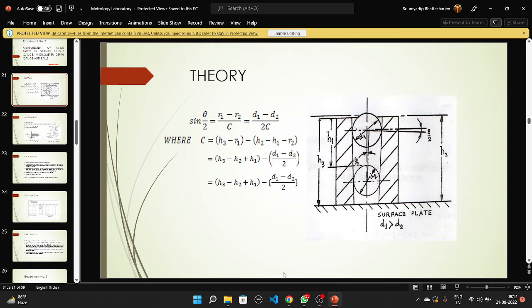Taper is basically the external taper. Now, the hole into which it is entering is also a kind of tapered socket, right? So taper in machine tools helps you in different ways. Taper is used in machines to hold and to align different component parts, like the center as